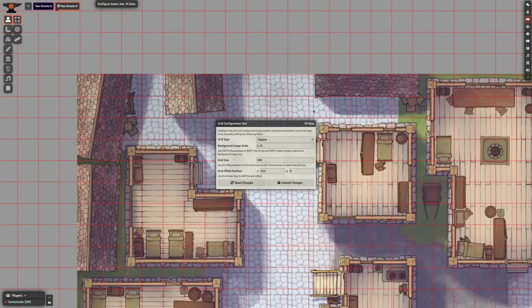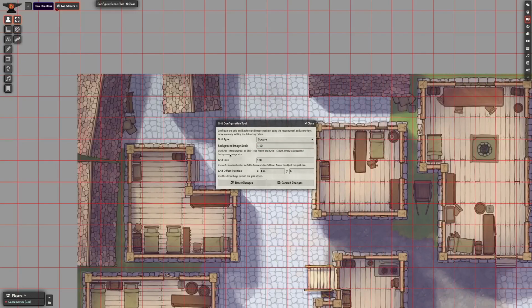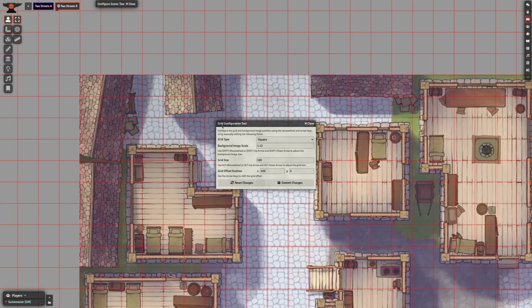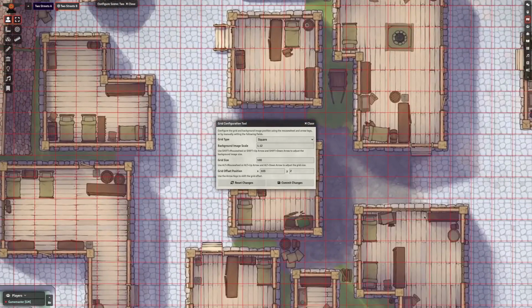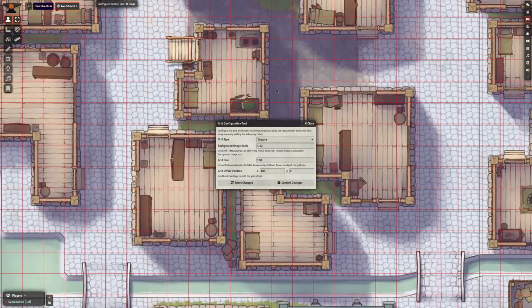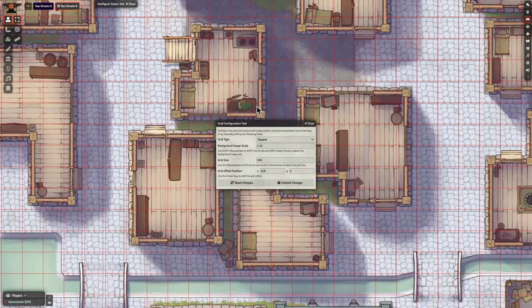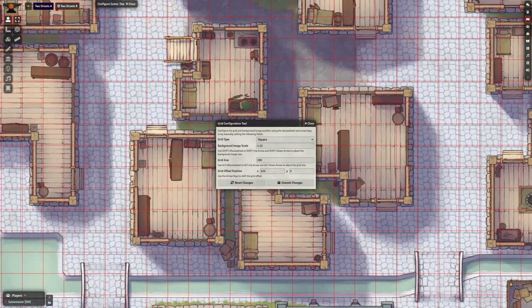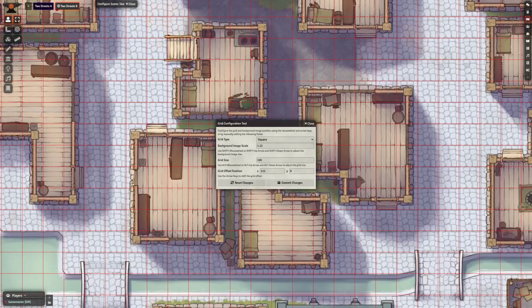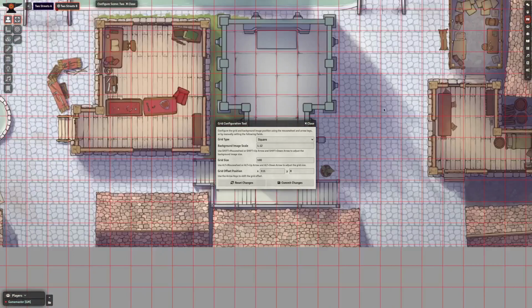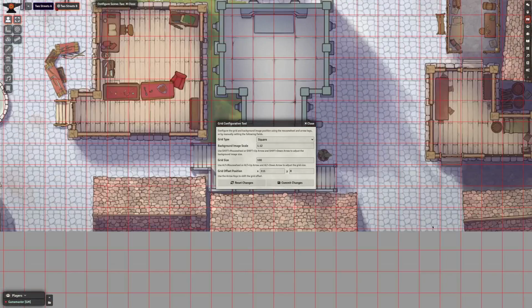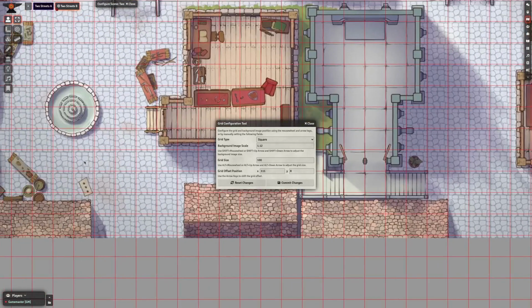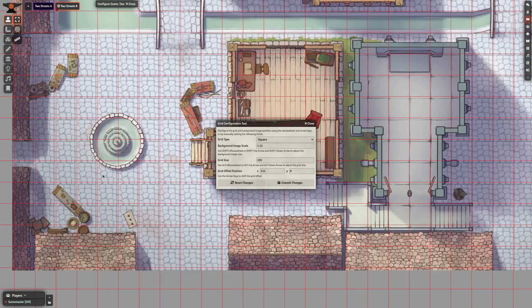And now it looks like our background image is too big. So we've got to back it off a bit. How about 1.12? Click, align, check again. Still too big, but only by a small amount. And in fact, if we went to the center of our map and ballparked the grid in around the middle here, which would look kind of like that, then even when we get out to the edges, these are actually basically close enough for most of what you're going to do.